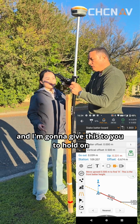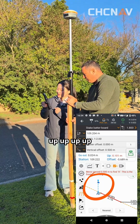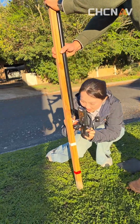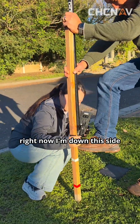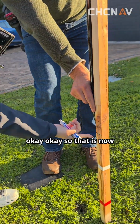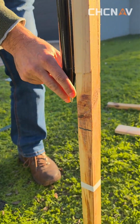And I'm going to give this to you, hold on, and you tell me when I'm at 0 cut, 0 fill. So we go up. Yes, and now you can make a mark for us exactly at that position. Make it in the front of the pole. Right now I'm down this side. There. Okay, this side. Yeah. Okay. So that is now 500 mils above the design level.